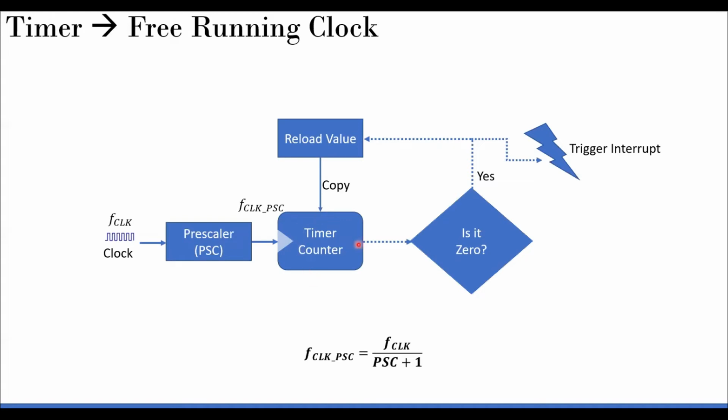And then you have a timer counter, and that counter you can load some value. So this counter you have the provision to count it up or count it down. There is a register where you have to write to that register that determines whether this will act as an up counter or a down counter. The initial value from where you want to start the counting in the case of a down counter, or the value to which you want to count up, can be loaded. This is a user control register. Again, you load the value here. That value will be the value to which the counter will count up to or count down from, rather.